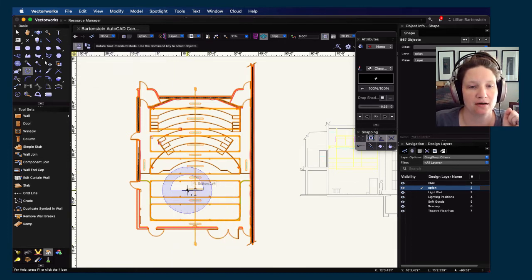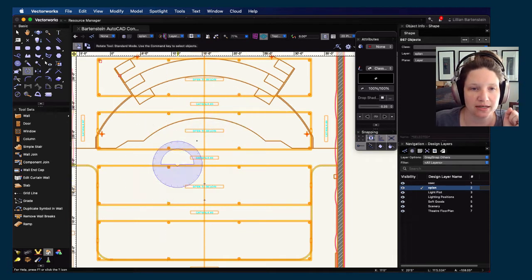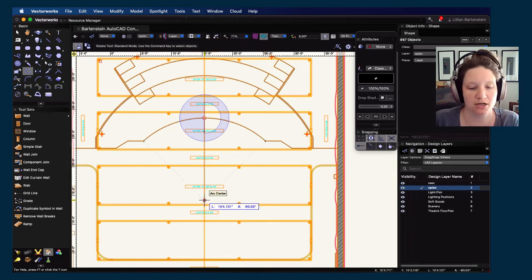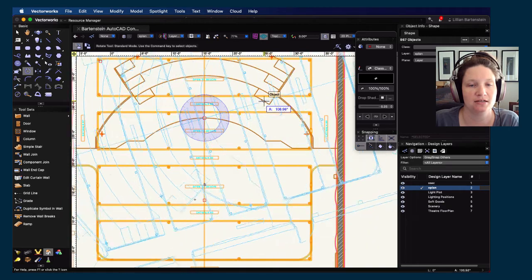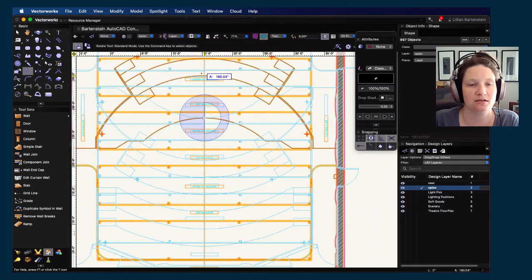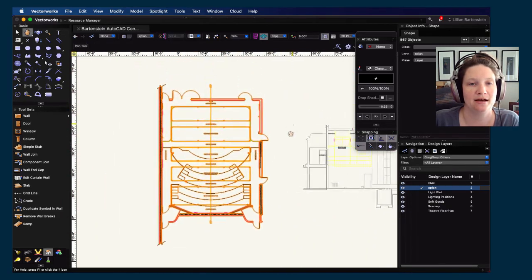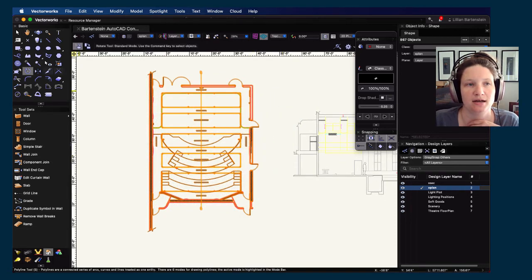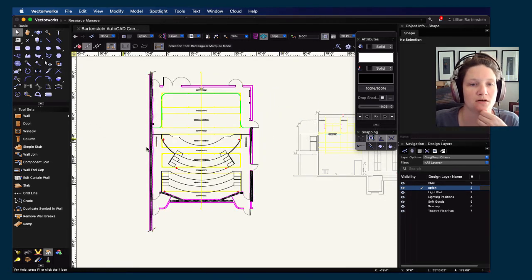I'm gonna pick something along the center line, somewhere in the middle, right? So the tip of the stage is usually a good spot. I'm gonna grab a straight line down from there, and I hold Shift to make sure that it's straight. And then I just rotate around, and now my theater is right side up, okay? Wow, yay. Okay, so those are my initial setup steps, okay?